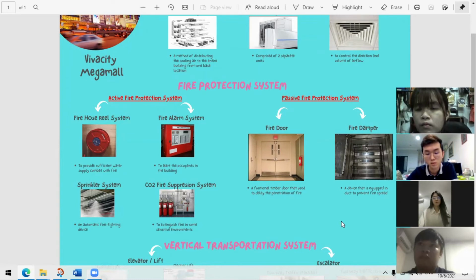In terms of operations, it is just like how we use a normal door, but a fire door shall remain closed at all times. But there is another case where the fire door is operated by electromagnets, which are connected to the alarm system. So whenever the alarm system is activated, it de-energizes the coil and releases the door from the electromagnets.